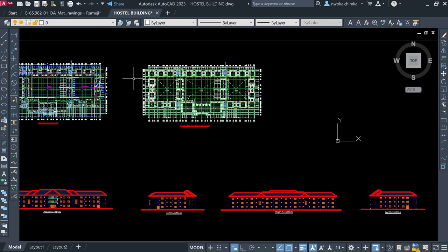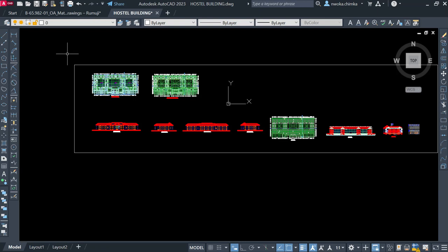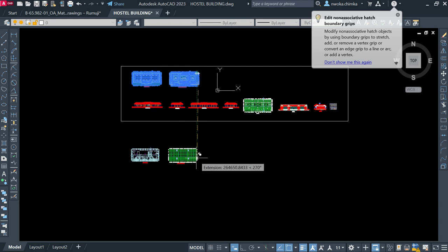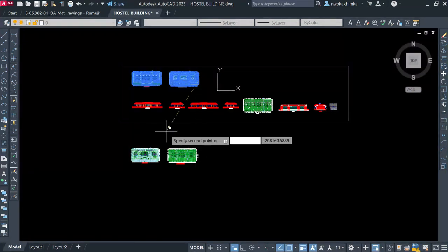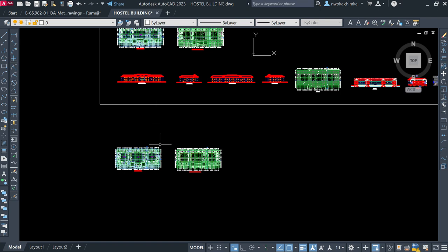dormitory or hostel building. So right now, once you get your building plan from your design architect, the first thing to do as a structural engineer is to copy the floor plan out. So you always copy the floor plan out. Don't begin your general arrangement drawing, which simply means your column position and your paneling, on your original plan. So always try to copy it out so that you can have a backup in case you make any mistake. You can just refer to what you have there.